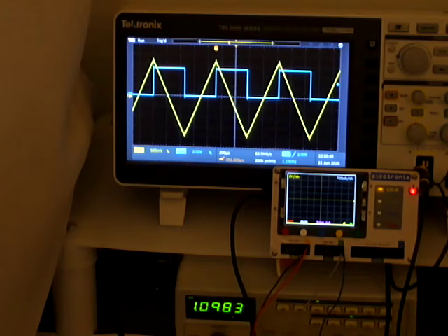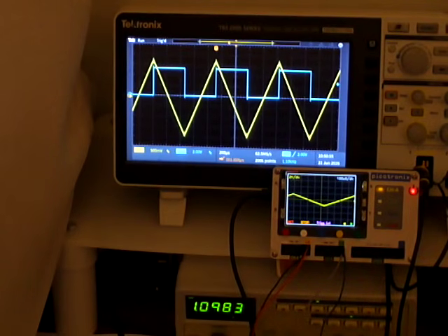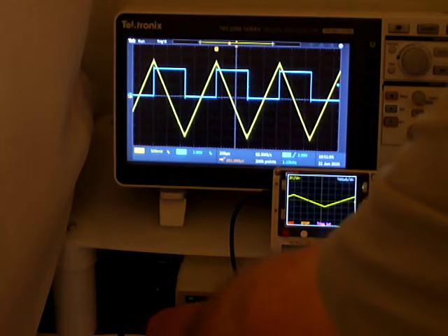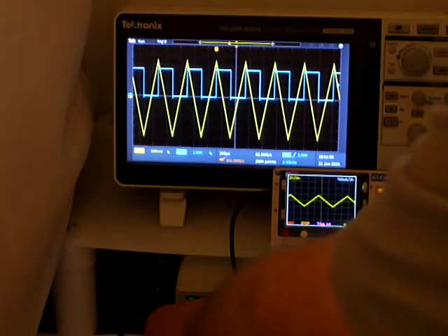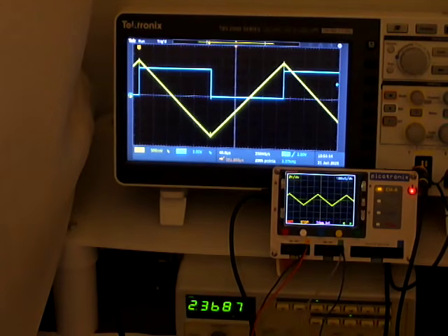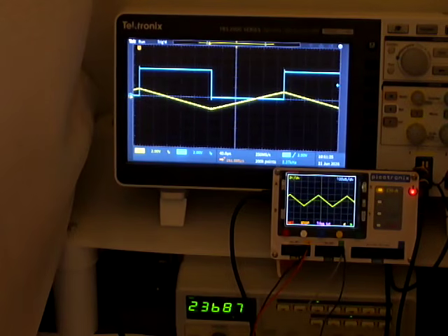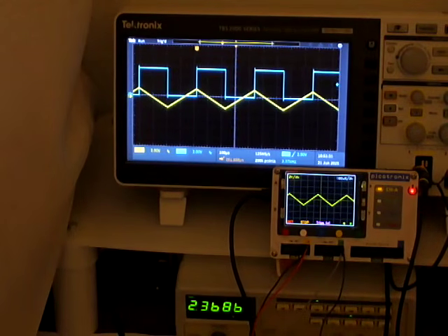So first of all we'll press the run button, and there we see we've got the waveform, and so we can change the frequency to get a different wave shape. We'll adjust the Tektronix to match it. So there we're seeing on channel A. Channel A is 2 volts per division. The Tektronix is 500 millivolts per division, so we'll put that to the same thing. And there we can see channel A is matching channel 1 on the Tektronix.